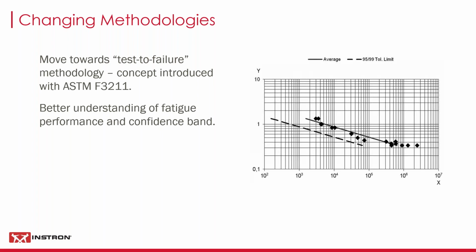So a very basic illustration here of a fatigue test. This is a materials fatigue test output. You've got a stress level on the vertical axis. You've got cycles to failure on the horizontal, and you see they're looking for a linear region, and they're looking for a plateau at the bottom, below which then it won't fail in any realistic time frame.